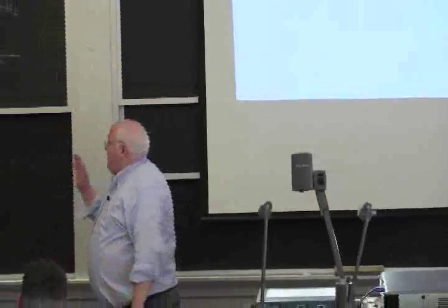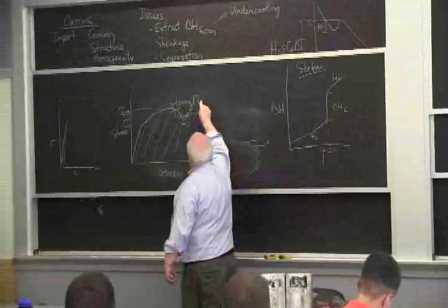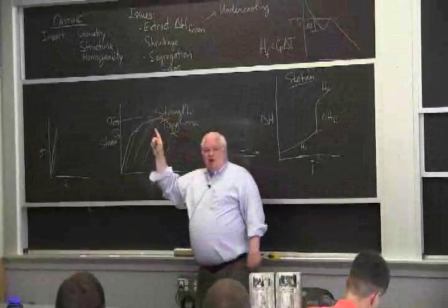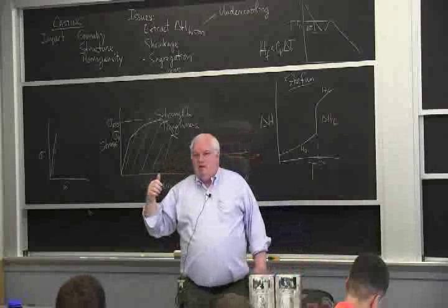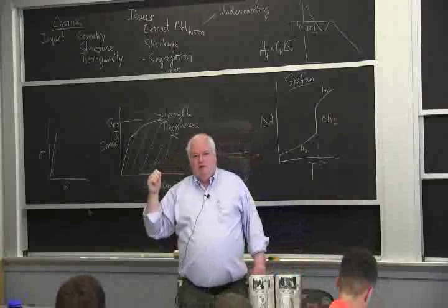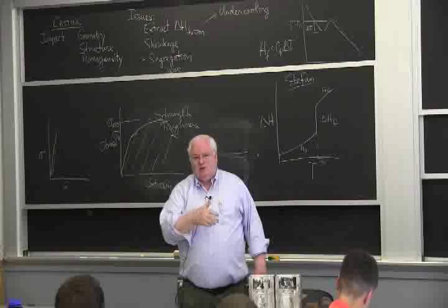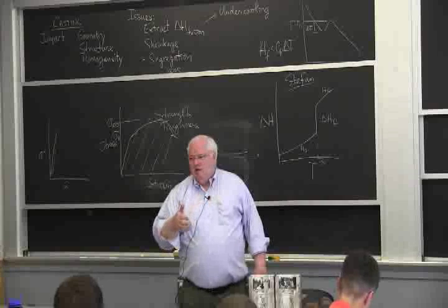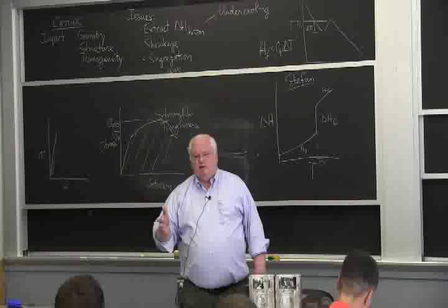So the one thing in metals that will give you both strength and toughness is fine grain size, okay? You want both. The Liberty ships taught us you want toughness. We knew about strength in 1880. That's when they first started doing tensile tests. And that was the specification until the 1950s.